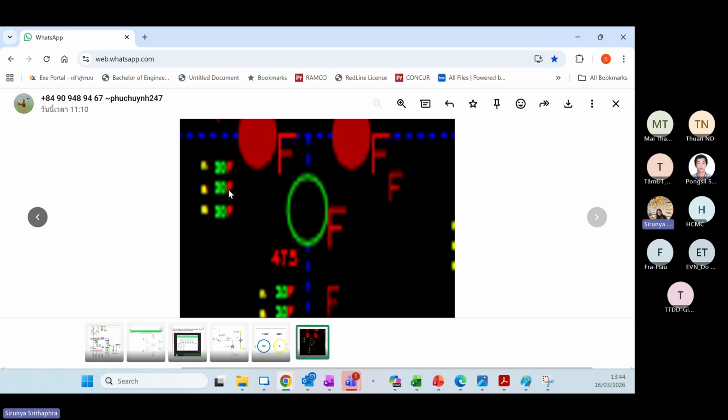Also, if they don't send back the signal list, they will put fail too. That means when the system collects good quality and a complete list from the GI command, it decides it's a good signal. We are using this for the IEC 104 protocol. I don't know if other protocols do this or not.